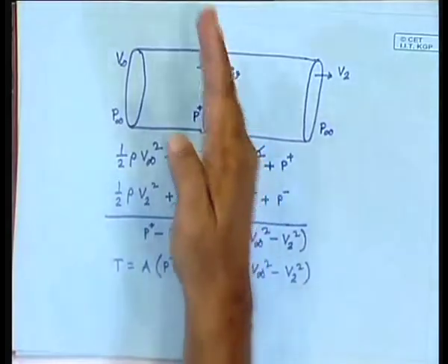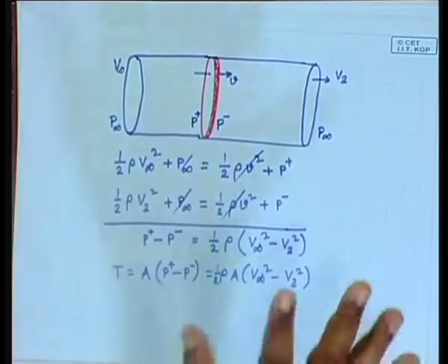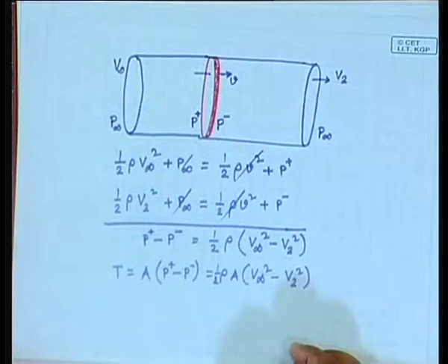That is the ultimate maximum efficiency that you can reach. But you will notice that here we considered some kind of a disk that remains there and extracts energy. Obviously, it does not work on the thrust principle. If it worked on thrust principle, it would recede, right.